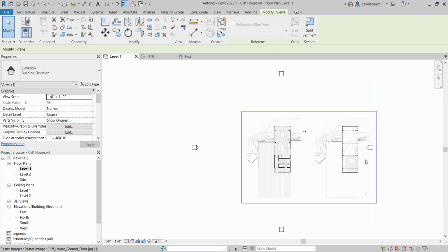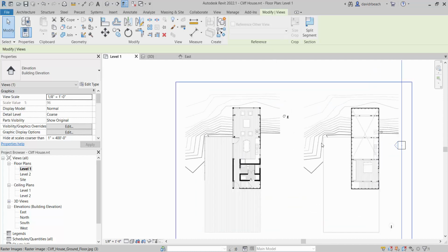But if I think about standing and looking in this direction, I don't have a reference plane. I don't have anything to draw lines on. Okay? So if I need to create something in elevation view with a custom component, I actually need to create something to draw those lines on. And the process of doing that is called creating a reference plane. You can think of a reference plane as a virtual piece of paper in your 3D model that I can draw on, right?